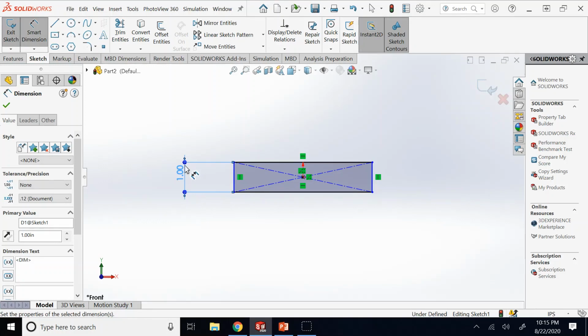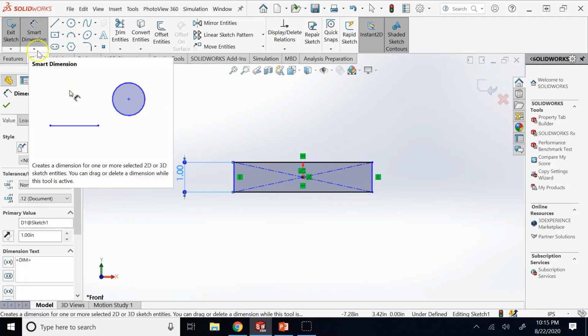While in CATIA probably you experienced, if any of you work with it, that once your sketch that you first draw and then want to provide dimension is way bigger or way smaller than actual size, and you provide a dimension to the first one, then it distorts the shape of the rest of the sketch, okay?